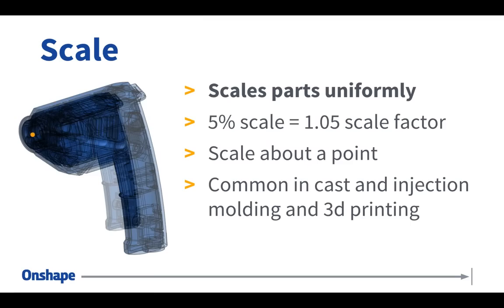Instead of moving a part or rotating a part or any of those types of things, this actually changes the geometry. It actually scales the part to match a certain factor that you've inserted. Now, this is a very common operation if you do any kind of mold design, injection mold design, cast mold design, where you have to deal with factors of heat shrinkage and accommodate for shrinkage within the design.